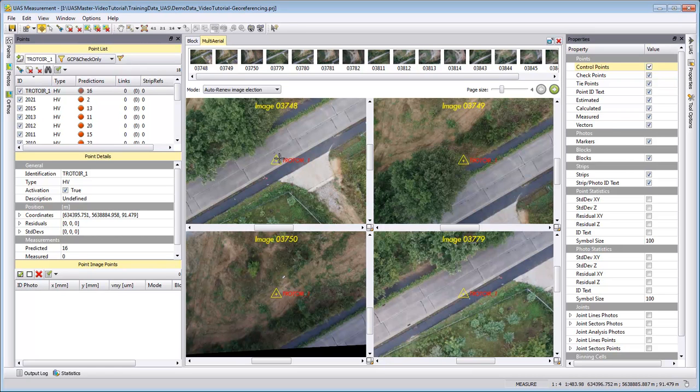We don't use high precision GPS here, so our GPS is something around 6 to 10 meters accurate. Additionally, we also have height changes in the terrain. So the position of this prediction is somewhere around 6 to 10 meters around the control point, but it can also vary and go further away if our IMU is also not good and the camera is looking at a different position than we assume.